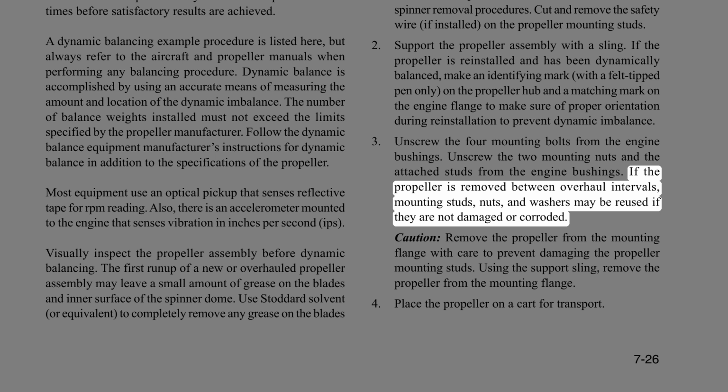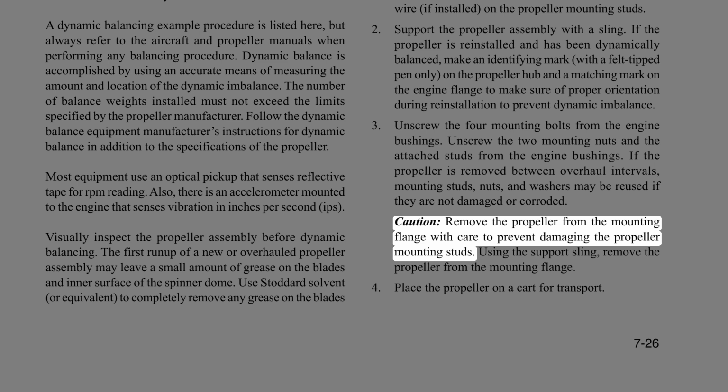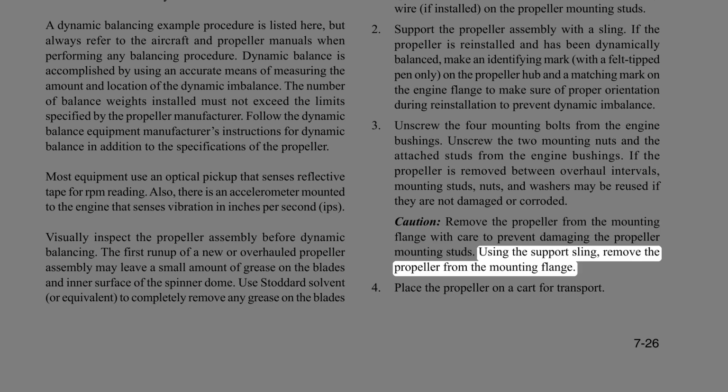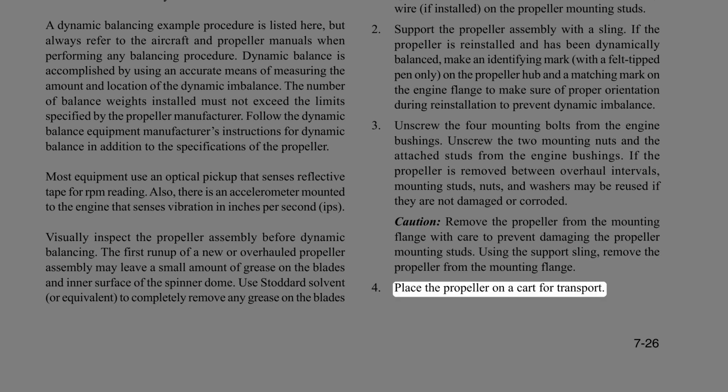If the propeller is removed between overhaul intervals, mounting studs, nuts, and washers may be reused if they are not damaged or corroded. Caution: remove the propeller from the mounting flange with care to prevent damaging the propeller mounting studs. Using the support sling, remove the propeller from the mounting flange. Place the propeller on a cart for transport.